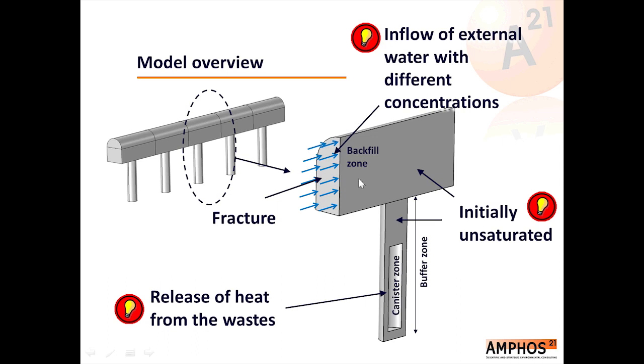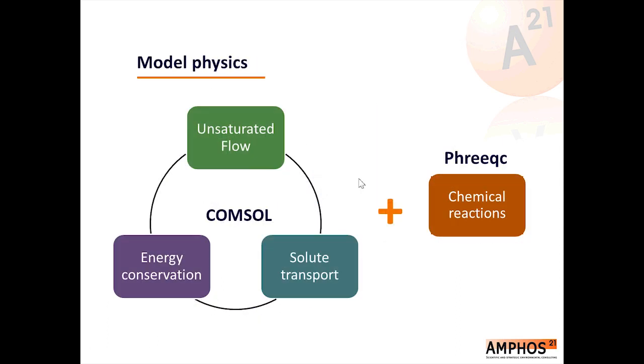So, in summary, the physics involved in this problem are variable saturated groundwater flow, conservation of energy, what can be seen also as transfer of temperature, and solute transport. And also chemical reactions. It is important to note that these 3 physics will be solved in COMSOL, but the chemistry part will be solved by the reactive code PhreeqC. PhreeqC is a chemical code widely known within the geochemical scientific community.